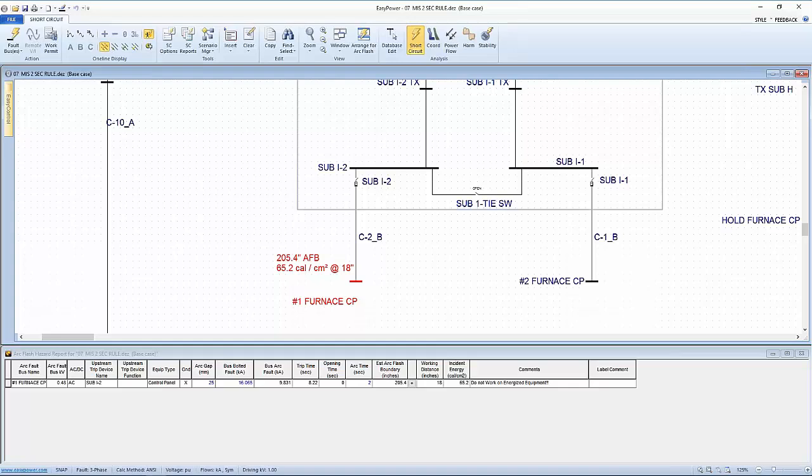Specifically, this fuse would trip in 8 seconds, but by default we've limited it to 2 seconds by that rule, and it's still at an elevated area. In my mind, it doesn't behoove me to limit this particular situation to 2 seconds. It's just someplace that I don't think anybody needs to be working on while it's energized, no matter what kind of equipment they have on.